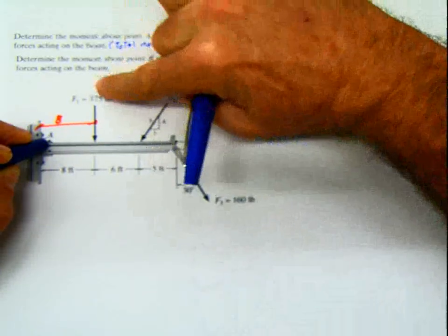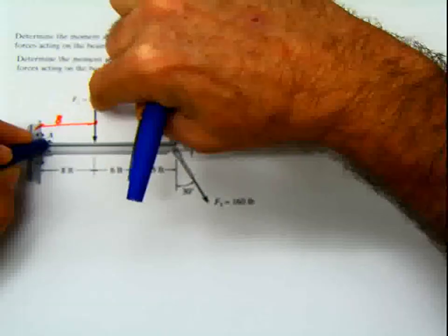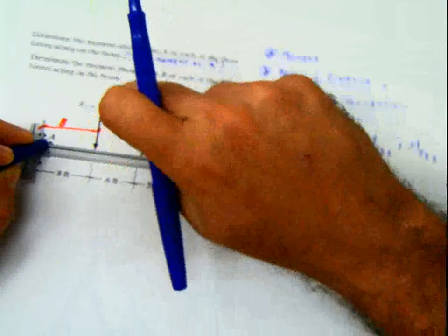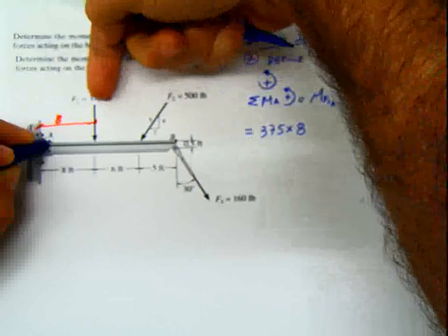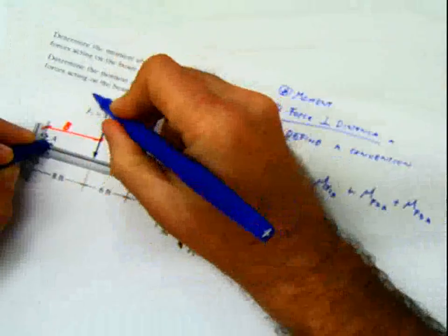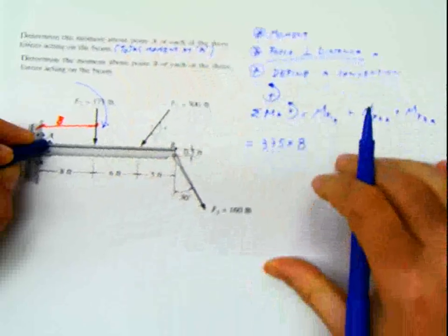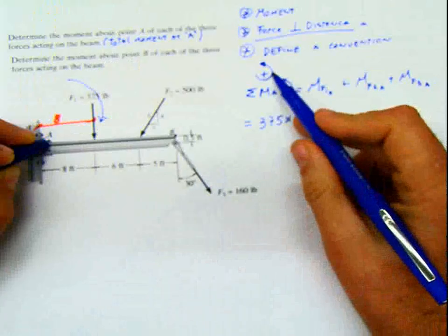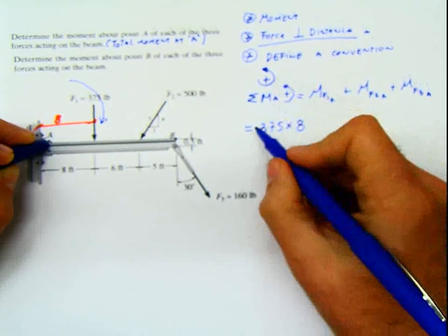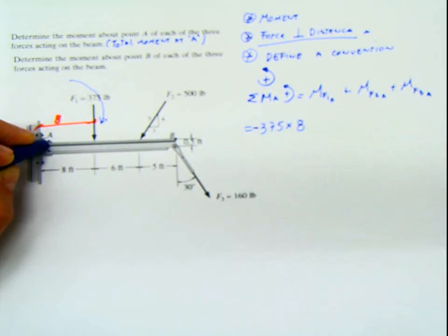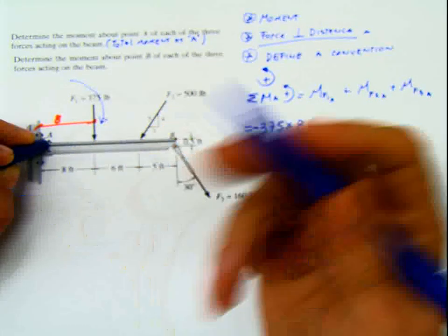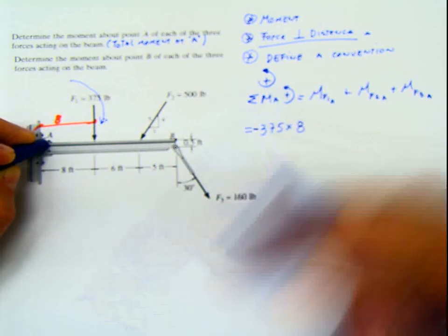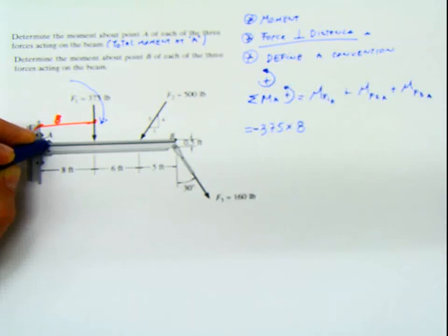And then I'm going to apply the force F in this direction because it's acting in this direction. Once I do that, you see what is happening if I keep the point A pressed there. Once again, when I apply this force in this direction, meaning there is a direction of rotation in this way, and that is clockwise, which is the opposite of my positive convention. Because of that, I'm going to put a negative sign here, because the tendency of rotation or the moment is acting opposite to whatever I define as positive. If I define positive clockwise, this will be positive.